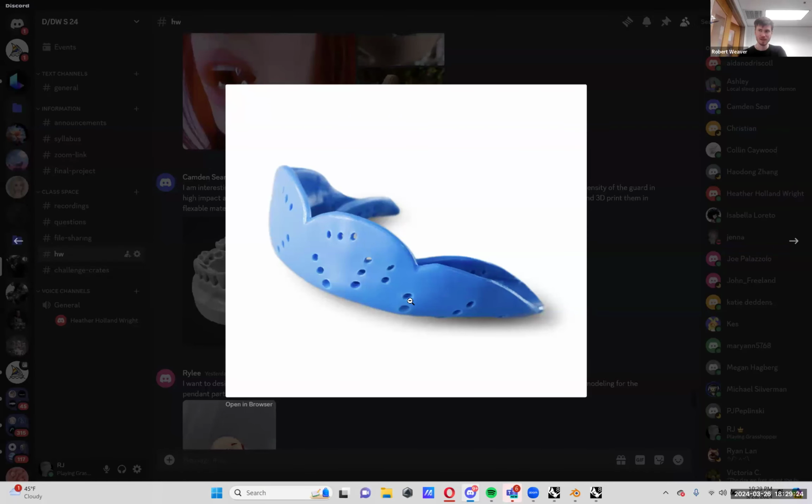And then once you have the 3D scan in Rhino, if you want to go with the Voronoi pattern, you could lay out a surface in Rhino that you design and then start mapping points and patterns onto that. All the stuff we've done with the Voronoi tutorials in the past should apply here as well, like attractor points for density. But that base form is most important. So for next week, if you're able to either make a mold or somehow make a form, I think that'd be a big first step.